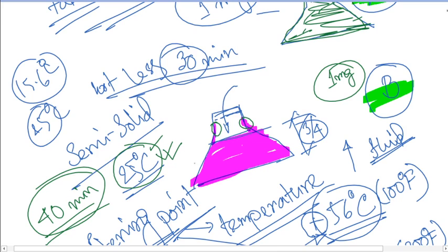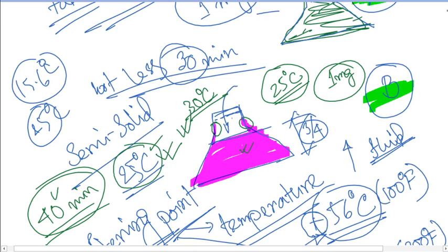We have just cooled it down to ambient temperature and we are taking the weight of this. So even if you take the weight in this particular volume, it may be at 30 degrees centigrade. For example, the weight will be all the same even if you keep it at 25 degrees centigrade as well. That's why we said to maintain the ambient temperature for 40 minutes. That will be enough for this particular bitumen, and we will be keeping the original test temperature after we pour the remaining portion with water, but not before that.